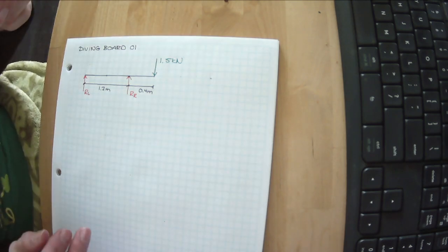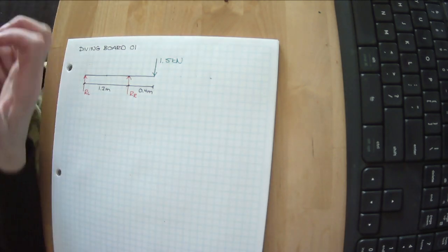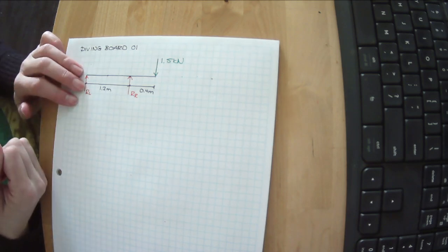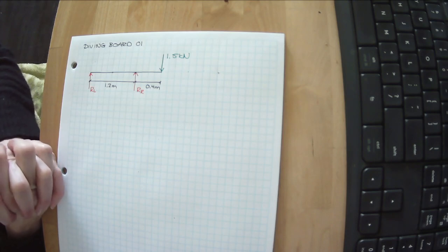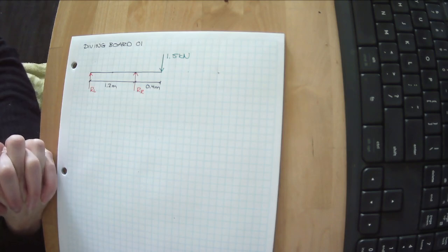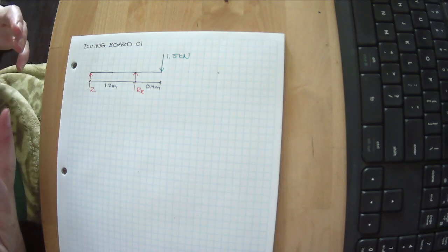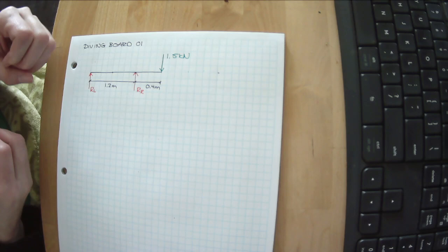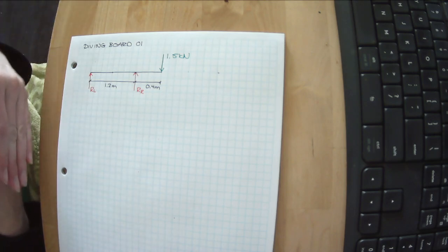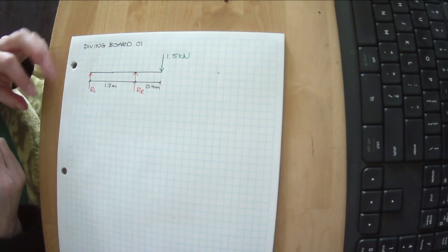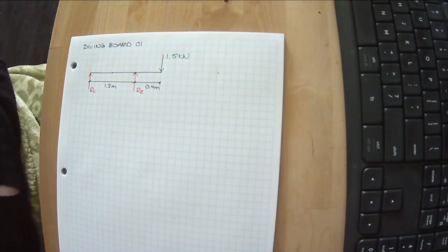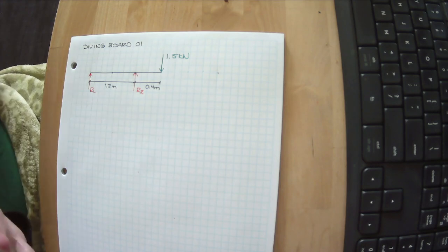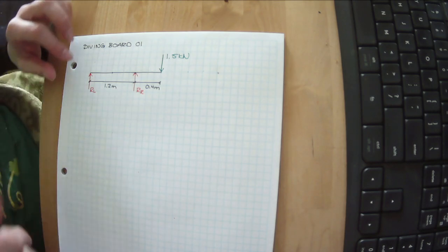How will we know if things are pushing up or holding down in our reactions? Here's a tip: always draw your unknowns in your positive direction. If you draw things in a positive direction, a negative number will mean you're wrong, meaning it's going in the negative direction. If I drew something in the negative direction and got a positive number, that would mean I was right. I know I'm confusing you right now. Let's go through an example.